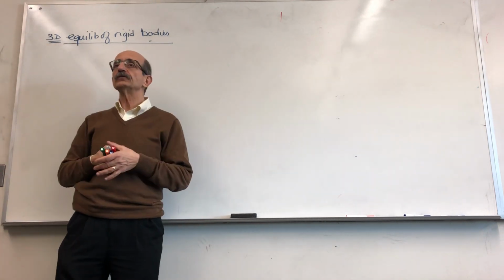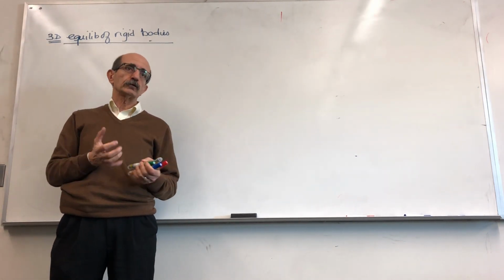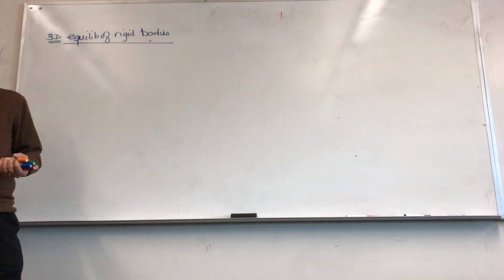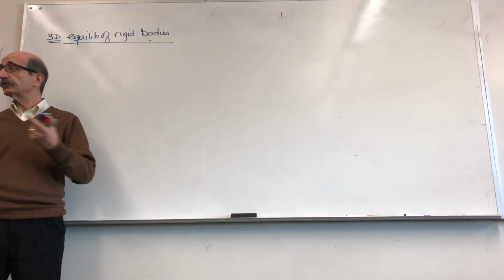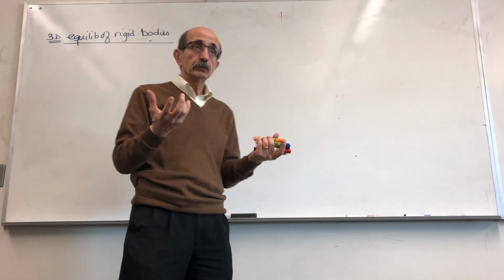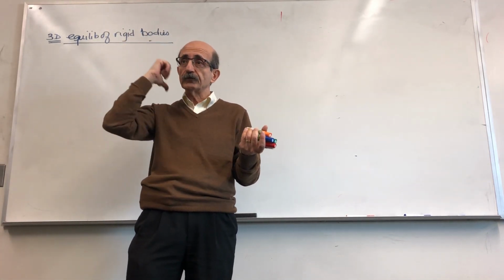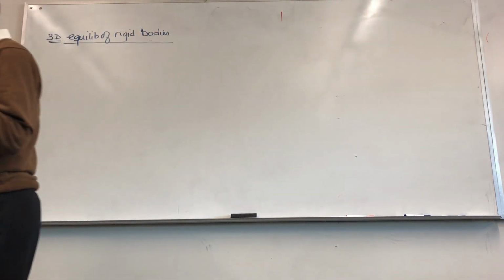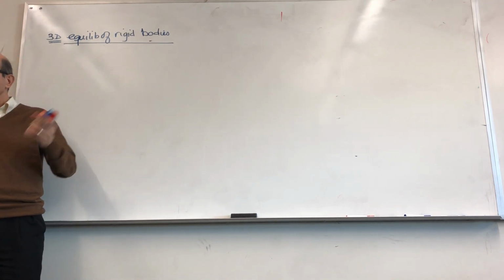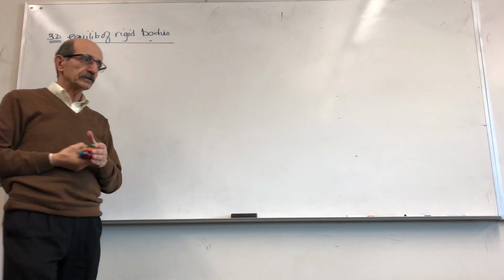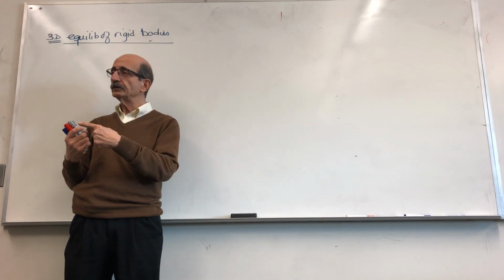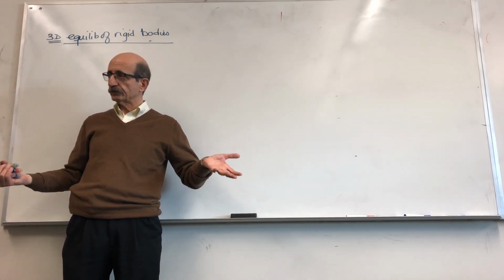In the case of 2D, the supports that are holding the structure in place have no more than three basic functions: resisting translational motion in X and Y, and rotational motion, which is only one direction, about Z. So we had this type of support, regardless of their shape or the way they are attached to the structure or their configuration, they either resist motion in one direction, two directions, or three directions.